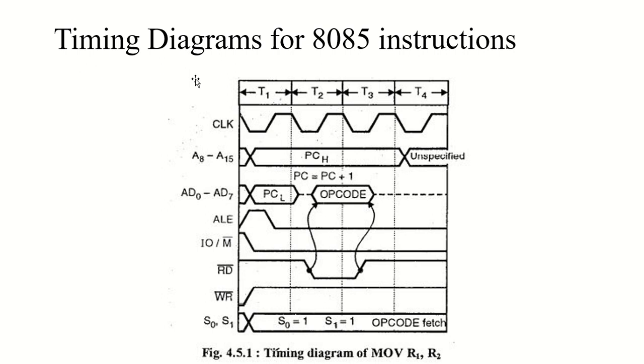Or, since I've told you that it is specific, let's say MOV RB, RA. Remember what we learned in the previous class: the register on the right hand side holds the value, and it will transfer the content to the register on the left hand side.